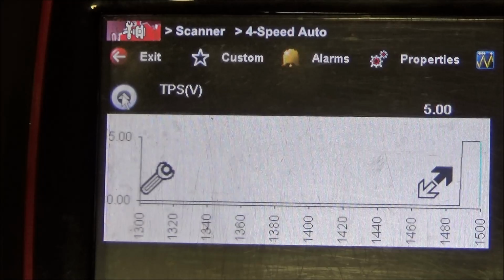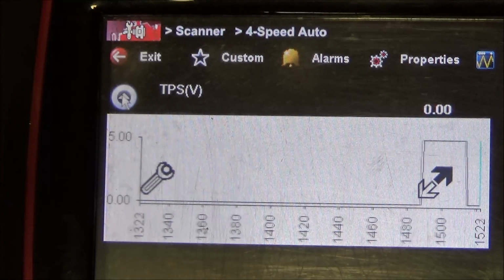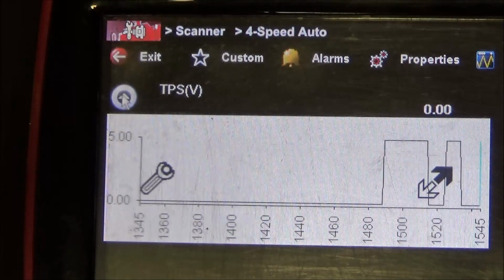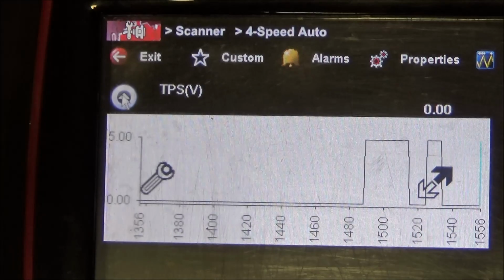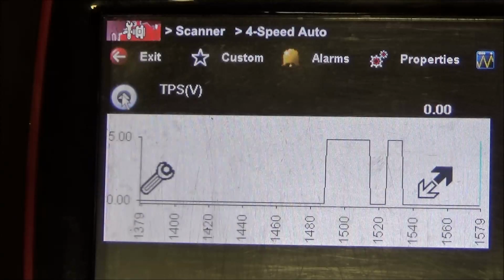So as we can see, guys, this voltage number is now pegged at 5 volts. I'm going to take this test light back off. I'm going to touch it on again and take it back off. So what that does for us, guys, is 1, it confirms that there's no short to ground on this circuit, and 2, it confirms that wiring integrity to the engine computer is good.